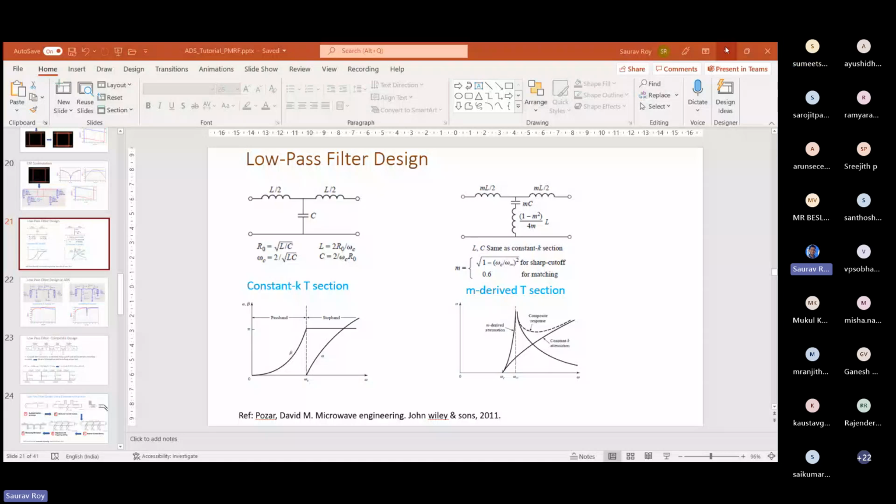That's why I have shown you how to tune a circuit. The normal circuit rule is, if you increase the length of a circuit, the resonant frequency generally reduces. It is inversely proportional to the length. So you can just increase the length a little bit and see if that reduces your resonant frequency. Sir, if you don't mind, I would like to share my screen and show my layout, whatever has been generated. Okay. Yeah, do it quickly.